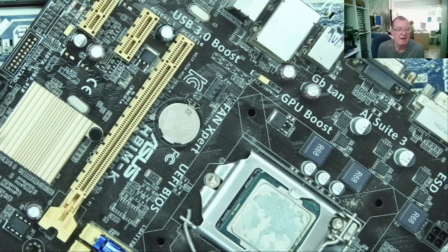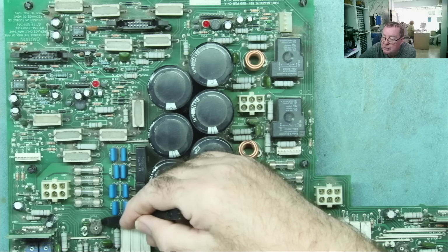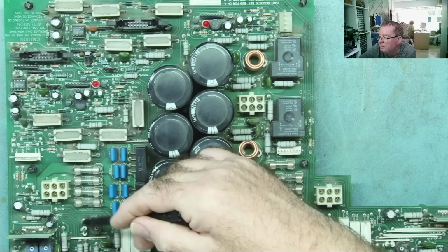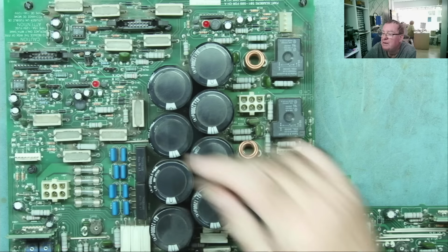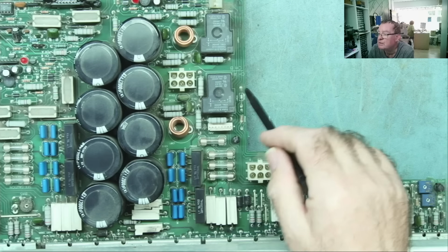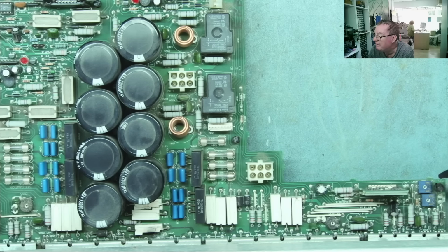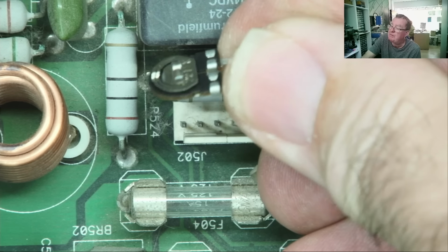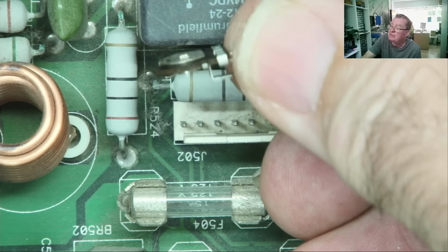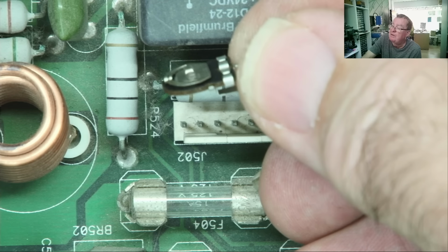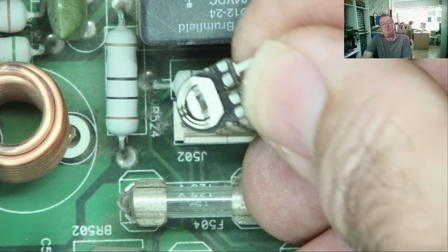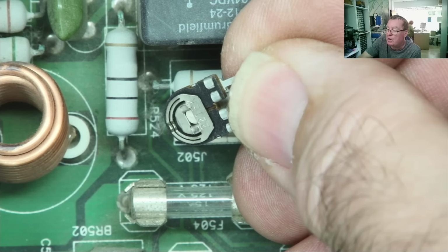And maybe even less obvious, but very common, trimmer pots. Sometimes they're closed like this, sometimes just an open track with a metal slider, which you can see. These are prone to failure, especially old ones. And these have a metal slider which makes contact with the carbon track. Here is an example of a trimmer pot with an open construction, so you can actually see the metal slider which is pressing against the carbon track. These are particularly prone to failure, again, especially in old electronics.